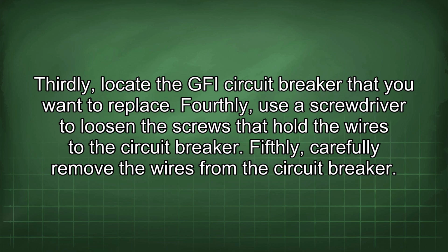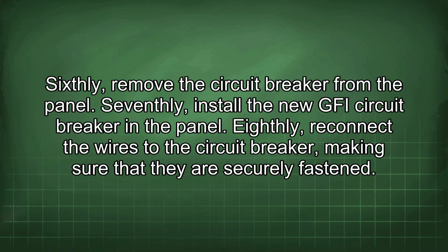Fourthly, use a screwdriver to loosen the screws that hold the wires to the circuit breaker. Fifthly, carefully remove the wires from the circuit breaker. Sixthly, remove the circuit breaker from the panel. Seventhly, install the new GFI circuit breaker in the panel.